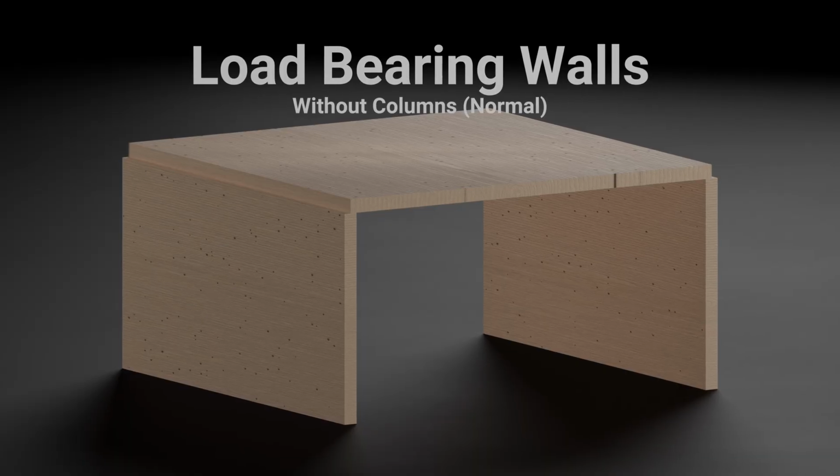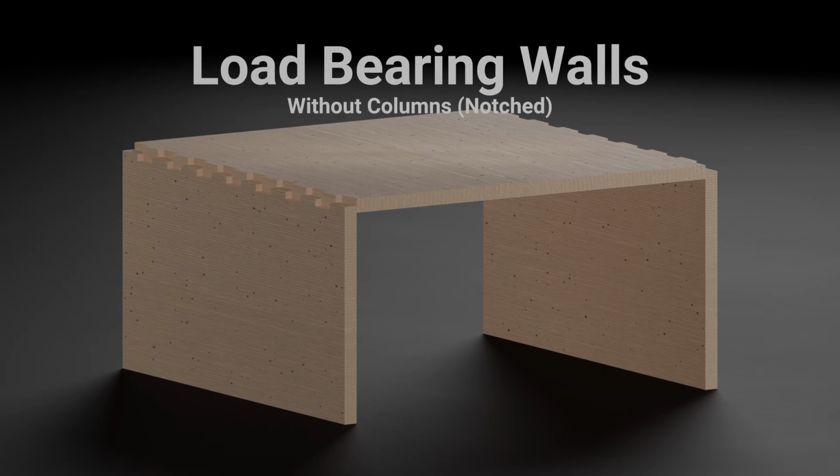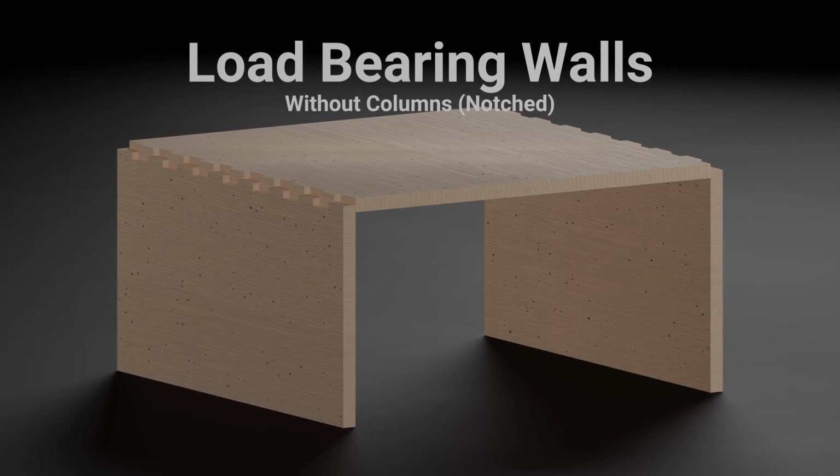In systems without columns, there are two main approaches. The normal approach relies solely on walls for structural support, offering simplicity and efficiency in construction. Alternatively, the notched variant involves the edges of the walls being notched to interlock with perpendicular walls or structural elements. This technique can enhance the connections and increase overall structural integrity.